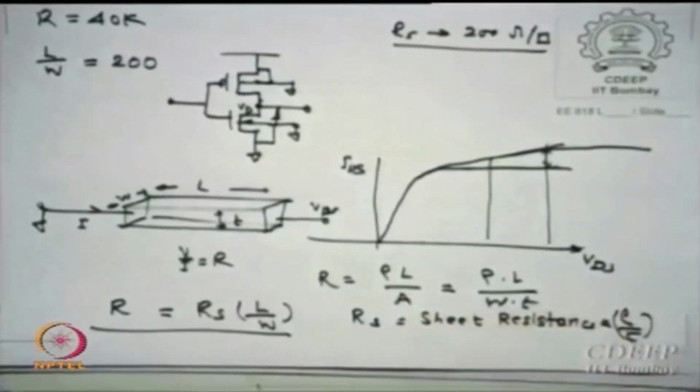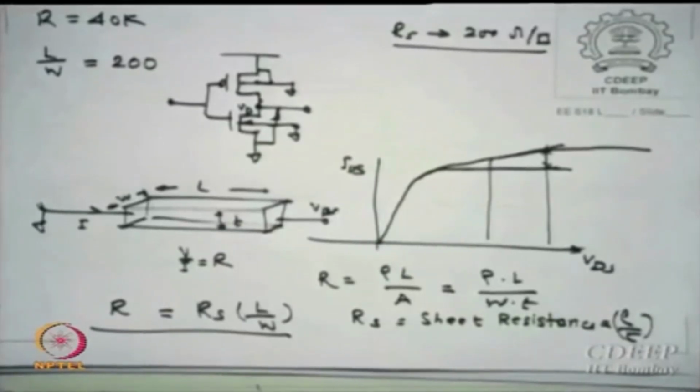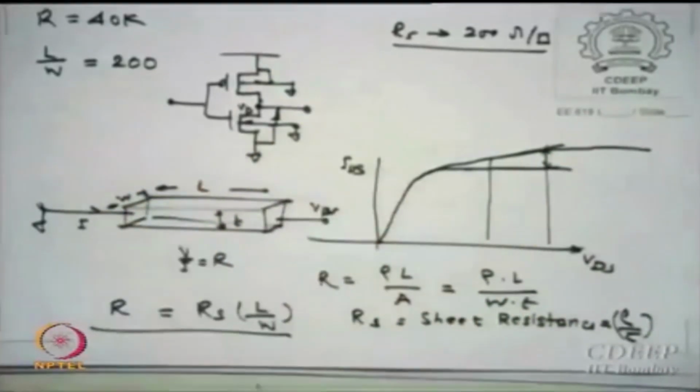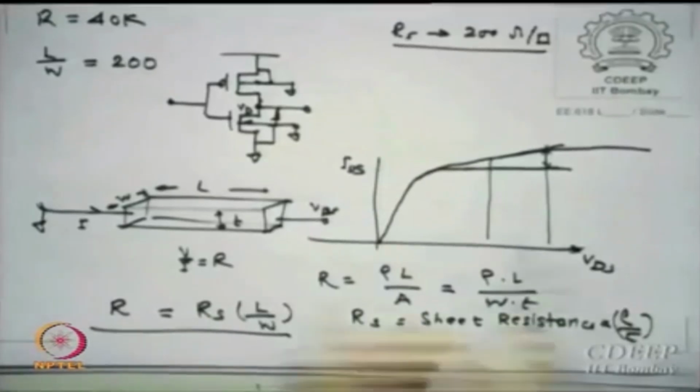So in an analog circuit, preferably transistors will be used as resistors. Of course, one can save some area, how? Anyone? No. So how do I do it? Spiral it or meander it, okay, something like this.